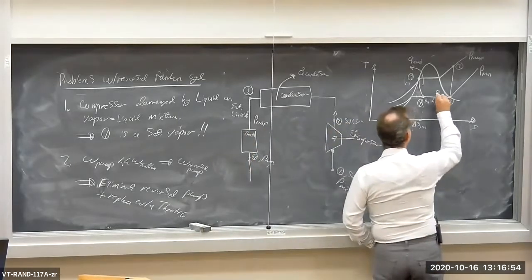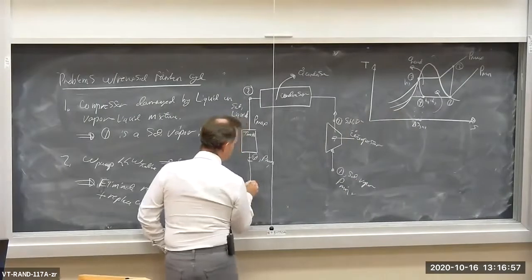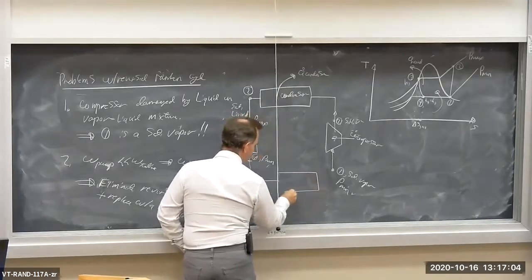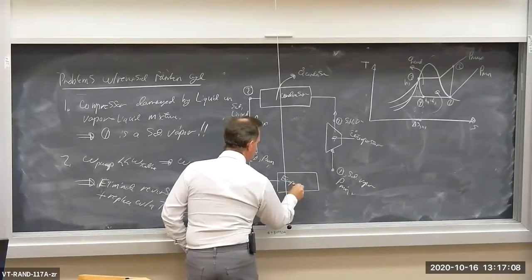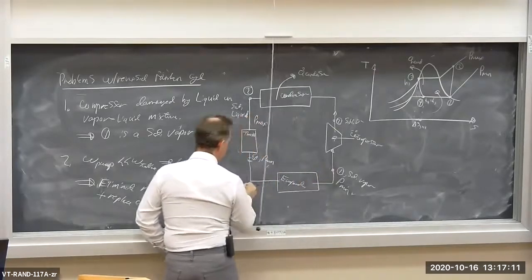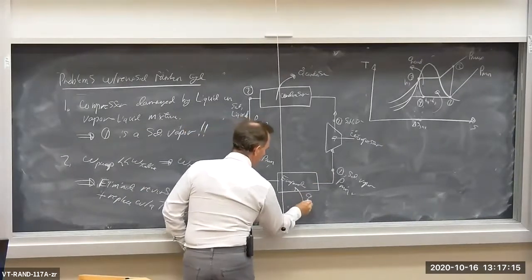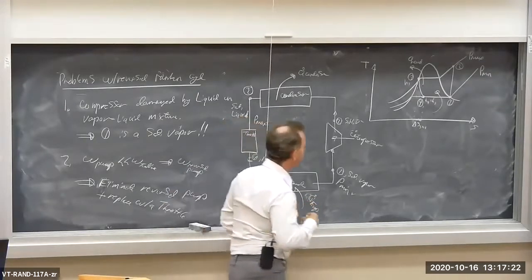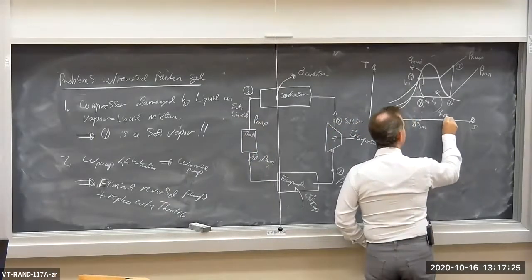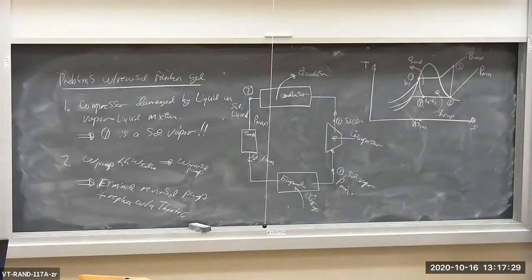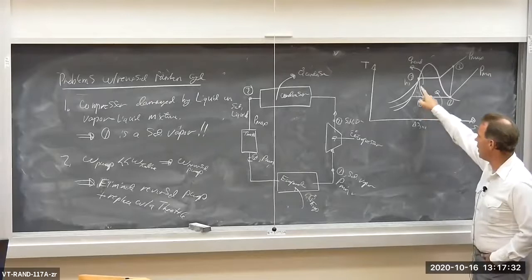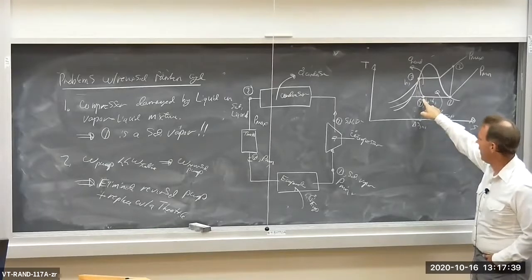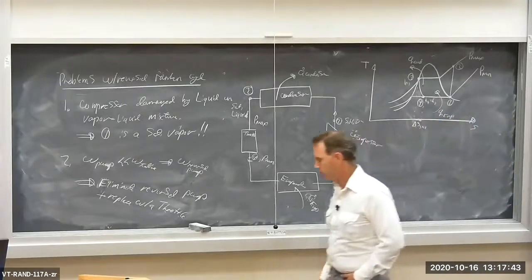And then we have the heat addition here in our evaporator. So 4 back to 1. So we have Q dot evap. Evaporator heat addition. So this is where our heat, Q evap, this is where our heat goes in. You can see here that if we have a saturated liquid at the maximum pressure, the working fluid going into the evaporator will be a mixture of vapor and liquid. So it's going to have some quality at state 4.